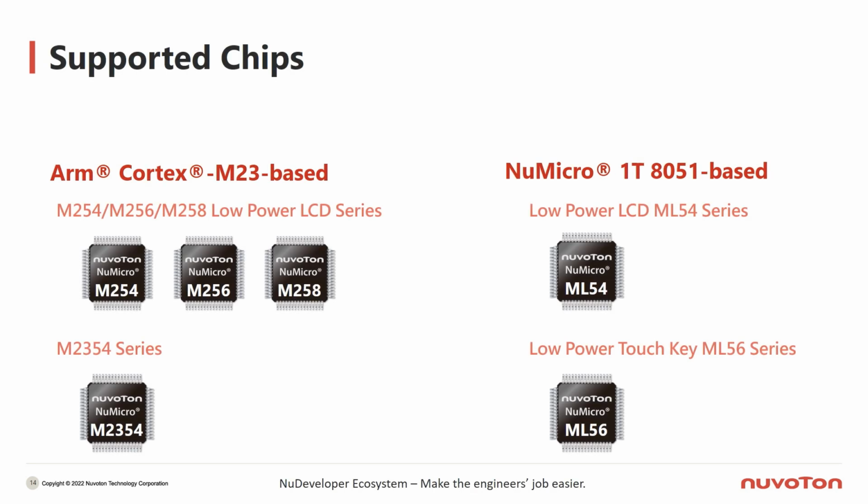As for the supported chips, currently, we support several Nuvoton product series, which have LCD driver functions. One is ARM Cortex-M23 based: M254, 256, 258, and M2354. And other series are the 8051 based, which are the ML54 and ML56 series.